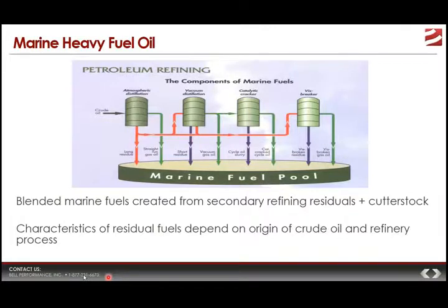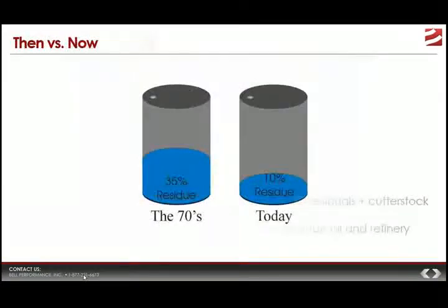So the reason why we mention this is because marine fuel oil characteristics impact how the fuel behaves when it's being used, and they have a definite relationship to the problems that the marine fuel oil brings with it. So when crude oil is processed at the refinery, it gets split into the different classes of products like gasoline and LPG, natural gas, and naphtha, and number one and number two diesel fuel, and those kinds of things get split into the different products that come out of it that the market uses, and by and large, these products get divided into either distillate products or residual products.